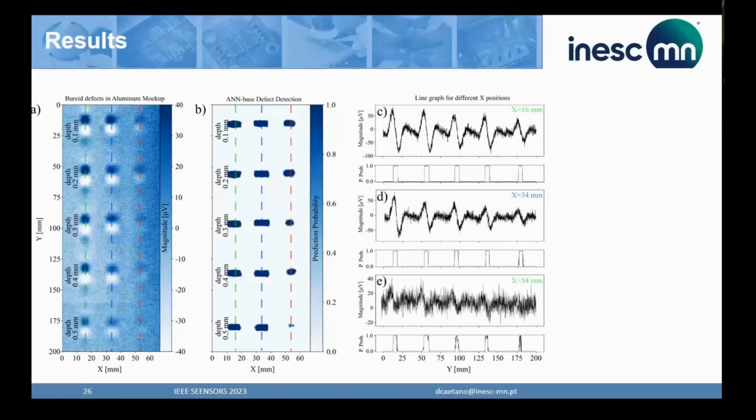The not so fun fact that I wanted to tell you is that when I presented these results, meaning that we can detect 100 micrometer defects at 500 micrometers of depth, to actual aircraft companies, saying that this is great, you can detect defects in plane wings much earlier, you can do whatever you do to fix them, they just tell me that they're not interested, because this is too fine, and if the plane crashes and you did detect this, then you are liable. But if you just detect the 1 millimeter diameter, which is in the regulations, and you don't detect this, you are not liable. So they are not interested in detecting such small defects, which is a little bit worrisome.